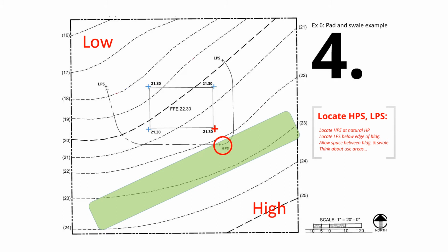But where exactly? The key thing here is to pay attention to all the slope requirements on the sides of the building. For example, in order to make the spaces around the building usable, there could be a common slope requirement of less than 5%. Or you may see other requirement that the center line needs to be at least some distance away from the building. Requirements like that, right?